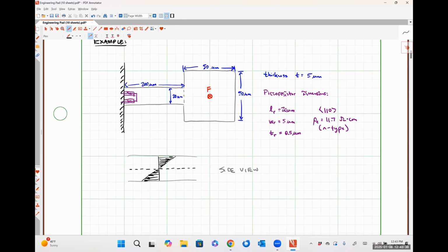we would observe. So if we were to make our piezo resistor too thick, so say thick enough to where it extended beyond the neutral line, some of that compressive stress would cancel out some of the tensile stress, and so we've effectively just wasted material because it's not doing anything. Another reason we might want to make it as thin as possible is because it's technically a different material than what the beam itself is made out of. And so if we make it relatively thin, we don't have to worry about what that material interface is doing.